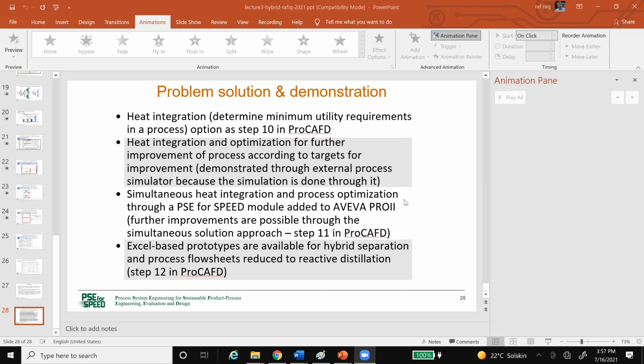Also, the pressure requirement. In a dividing wall column, we cannot have different pressures in the two sections. And if a pressure drop or different pressures are needed because of the compounds that we are separating, that is not possible. So very quickly, these are two that we know very well. It doesn't matter what the middle compound flow rate is, but the top compound and the bottom compound flow rates need to be sufficiently large.